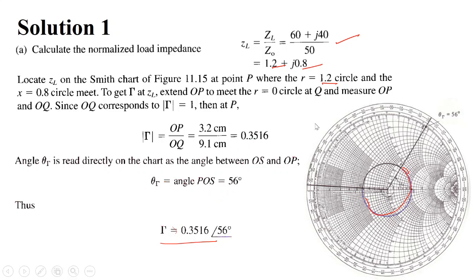So we have completed the Smith chart, and we have seen what the fundamental Smith chart is, what the basic concept behind it is, and how we can use it to find the different values of the reflection coefficient and the impedance, admittance, location of Vmax, Vmin, SWR, and other parameters. The Smith chart is frequently used in industry, and now in modern days we have very high computation facilities. So you can also do the same thing using formulas and programs, but still it is used, and it is generally used in load matching.